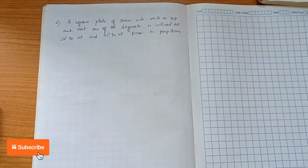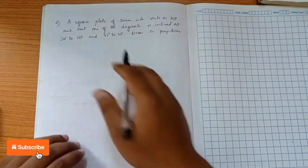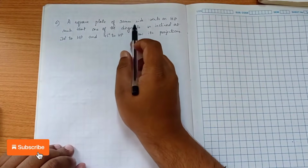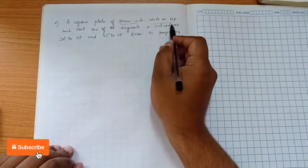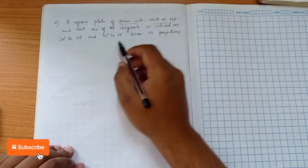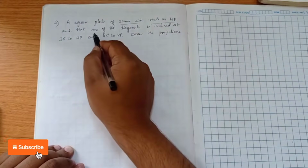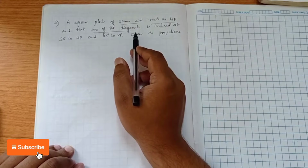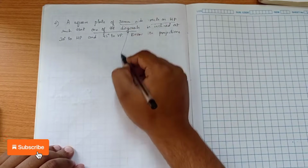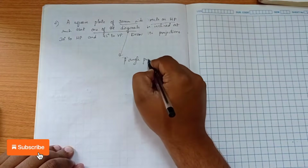So we learn another problem on a square plate lamina with respect to the beta angle. We will proceed with the question. In this question, a square plate of 30 mm side rests on HP, so the first position starts from the HP plane, such that one of the diagonals is inclined at 30 degrees. You can see that they have mentioned one of the diagonals. For a square, that means it is a beta angle problem, right?